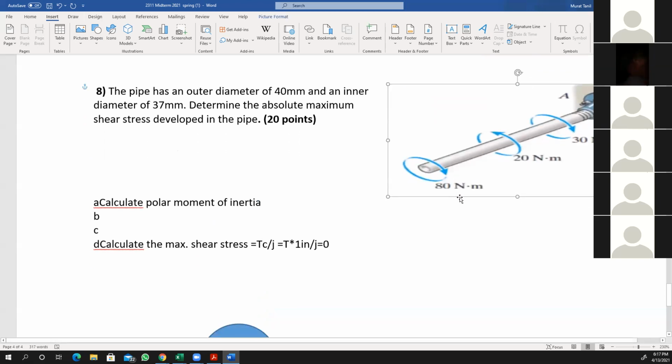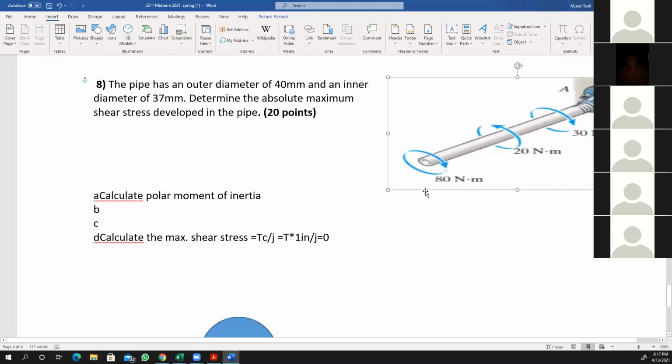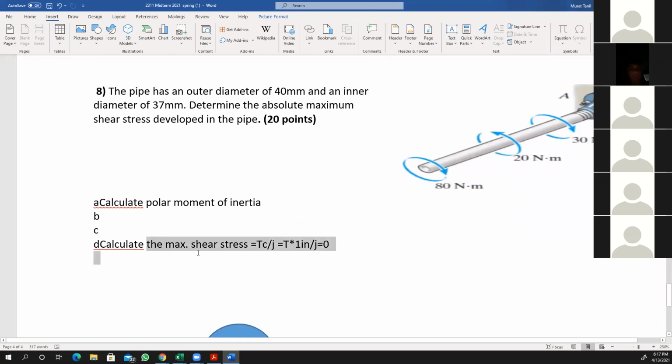That's why I can say this hollow shaft design is perfect against torsion, because you are saving material. You're taking the middle portion out, which you don't need. Do you need the middle portion if the service condition is only experiencing torque or torsion? No. Your goal is to reduce the maximum shear stress applied to this specimen and resist the shear stress forces.